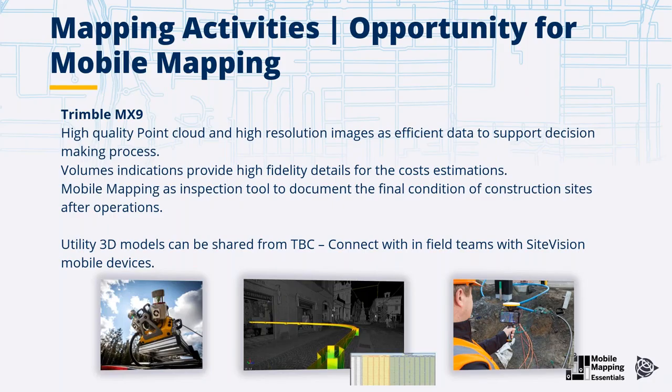With point cloud data, they would like to understand how much material has to be removed from the site, how many trucks will be needed to move this material somewhere else, how deep the trench will be, and how much material will be needed to fill in the trench as soon as the cable has been installed on the ground.